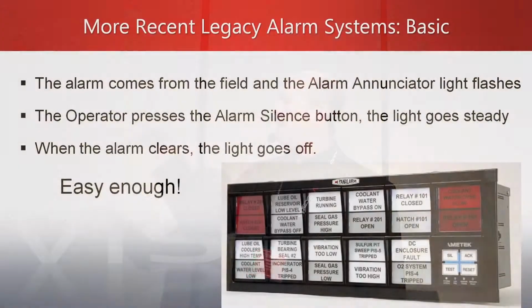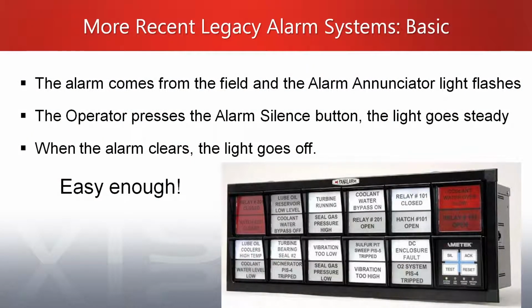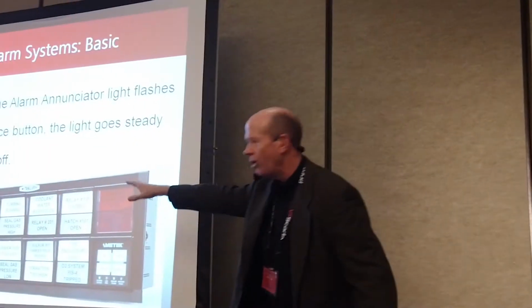And then that light would flash. And then somebody would come along and press that alarm silence button, or the acknowledge or silence, depending on which one it was, and the light would go steady. What that meant was the operator had gone over there, had acknowledged it was flashing, pressed the acknowledge or silence button, and it now went steady. And now when the technician came by and said, oh, by the way, you need to look at whatever that alarm happens to be, they go and they work on it a bit, and then hopefully it works.